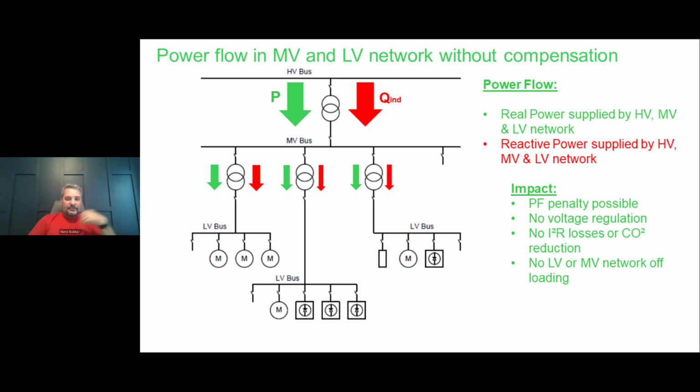So the impact of this, you can have a power factor penalty, you have no voltage regulation, increased I2R losses, CO2 emission, and no low voltage or medium voltage offloading of your distribution.